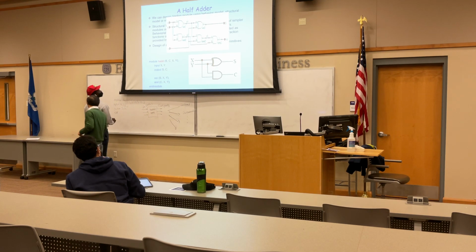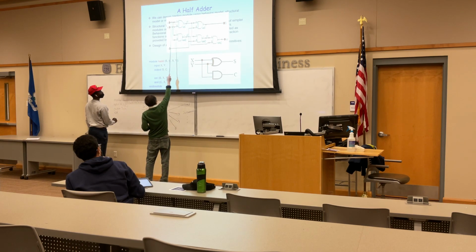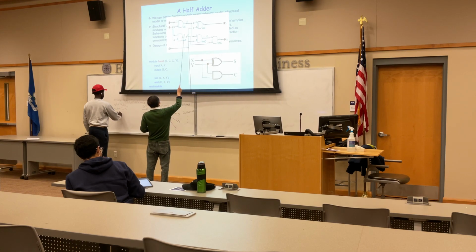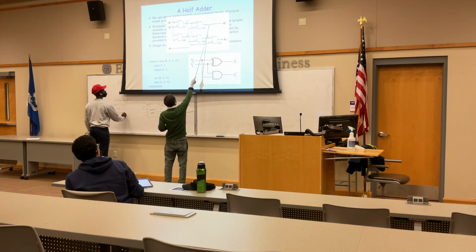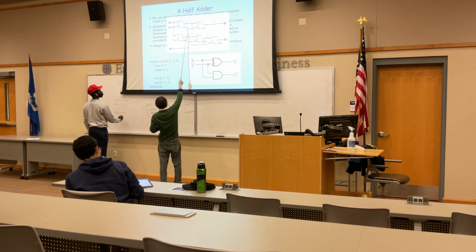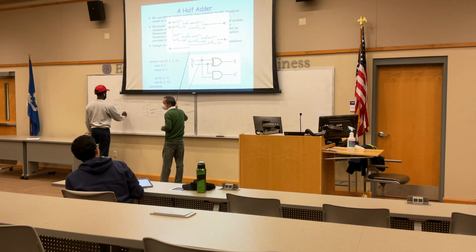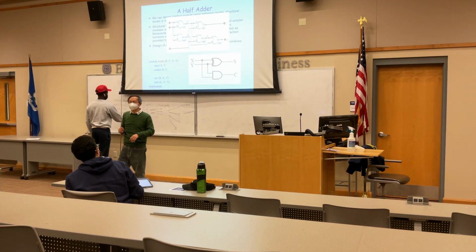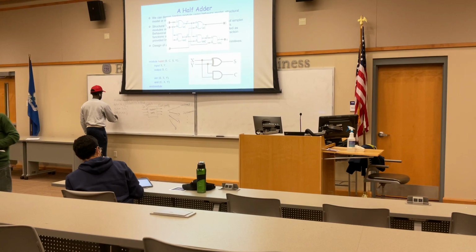Yeah, very nice. Okay, A, B, C, all that is very good. And then you say XOR is N1, A, B, right? And then NAND N2, A, B, and then XOR S, A, B. This A, B is not your actual A, B here. It's N1, N2, right? S, N1, N2. Your actual signal maps into the original design by the template.